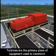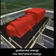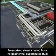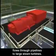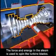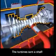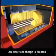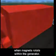Turbines are the primary piece of equipment used to transform geothermal energy into mechanical energy. Pressurized steam created from the geothermal superheated fluid flows through pipelines to large steam turbines. The force and energy in the steam is used to spin the turbine blades. The turbines turn a shaft directly connected to an electrical generator. An electrical charge is created when magnets rotate within the generator.